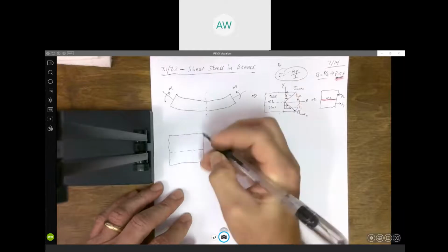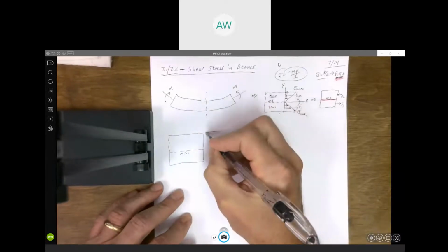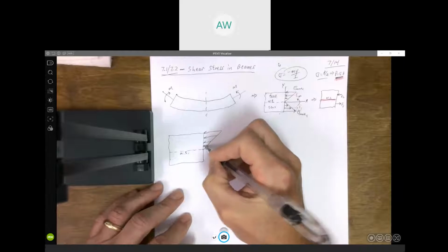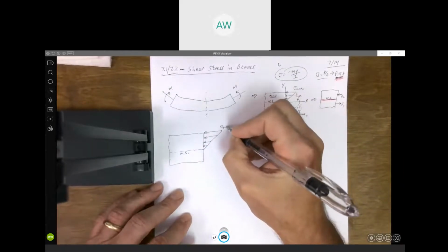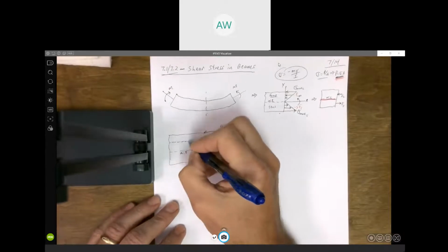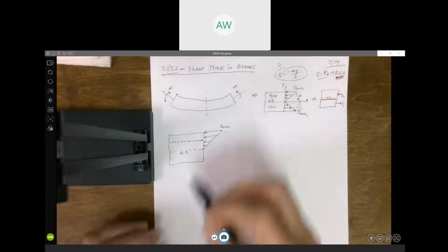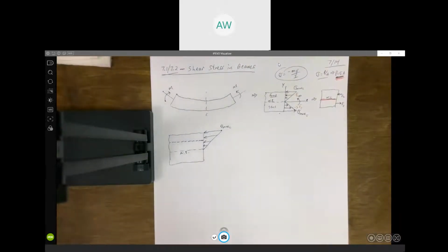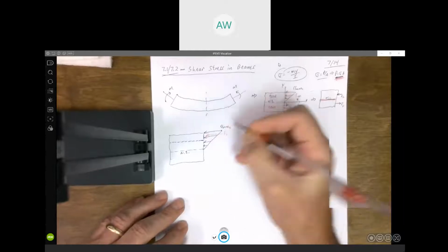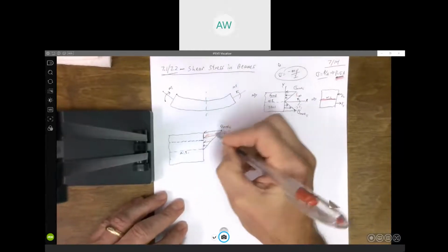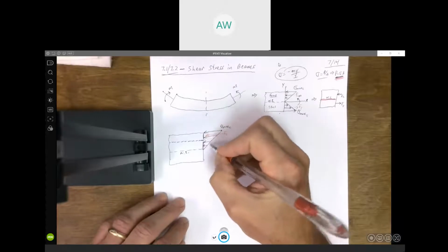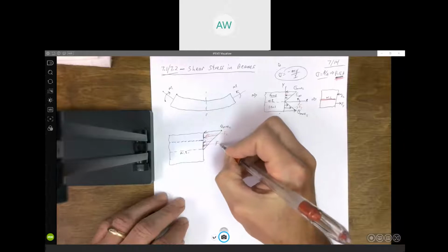All right, so let's again say this is our neutral surface. And let's just look at this normal stress up here above the neutral surface. Again, this would be our maximum. But let's take some other arbitrary surface here. Let's look at what happens along that surface. Well, we're going to get an equivalent force, I'll call it FC. If we just look at this part of our normal stress, we're going to get a different force if we just look at this surface. I'll call it FC prime.